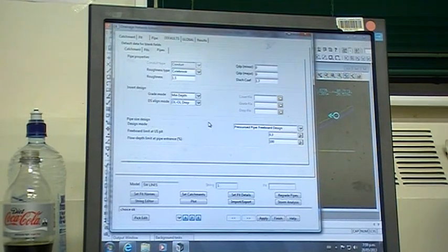That's accounted for, but it's preset in one of your files. So there will be instances, even under a 225 in and a 225 out, where that drop will increase, but it's only when that bend becomes tight, to allow for the loss through the manhole, the head loss. Make sense?